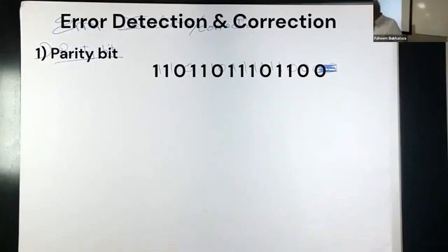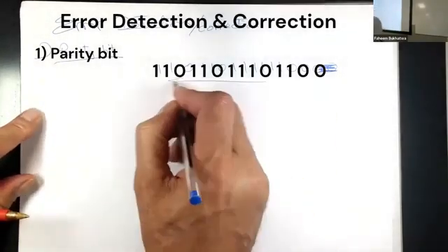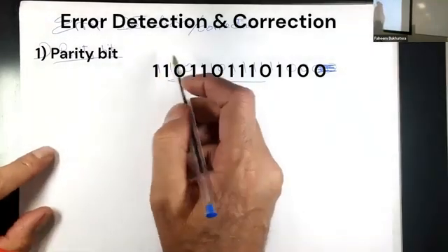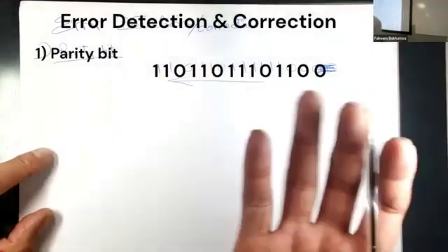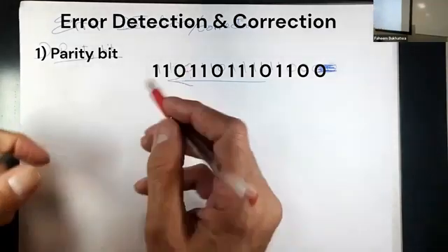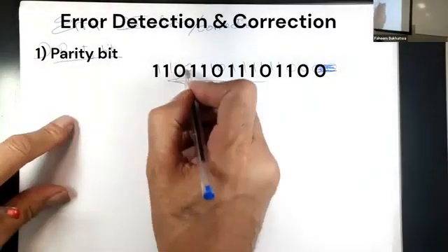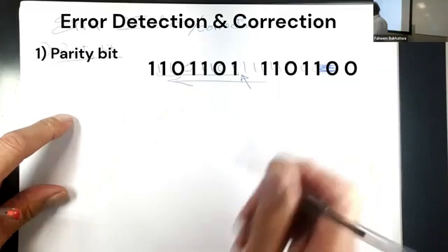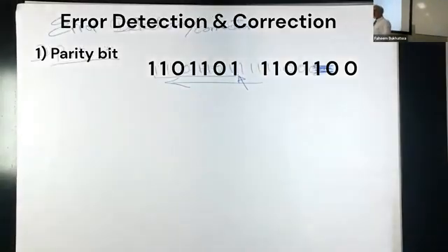So the way the parity bit error detection system works, it takes this data, and when it sends it, it adds more bits to it. Imagine this is the frame and this is the direction of transmission. This is the 8-bit parity error detection. It will take 7 bits of the user data, 1, 2, 3, 4, 5, 6, 7, and it will insert an extra bit in bit number 8.